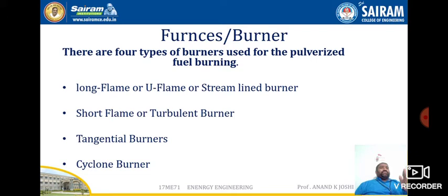Thus a good burner should meet some essential requirements in its design. Let us discuss some of the points for the burner. First, it should mix the fuel and primary air thoroughly and inject the mixture into the furnace, and it should create proper turbulence for air-fuel mixing and maintain stable combustion. It should also be able to control the flame shape and flame travel by varying the amount of secondary air.